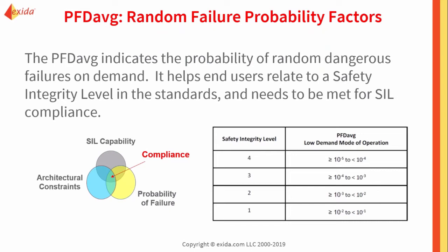So that calculation is directly responsible for a portion of what makes a device SIL compliant. It's one out of the 3 compliance requirements from IEC 61508 and 61511.